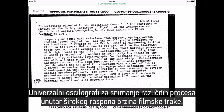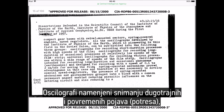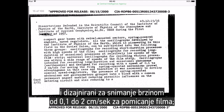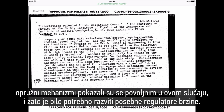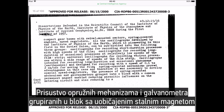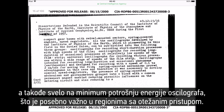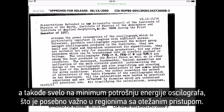of the film strip. Oscillographs intended for recording long duration and occasional phenomena, earthquakes, and designed for recording with a speed of 0.1 to 2 centimeters per second for moving the film. Spring-operated mechanisms proved advantageous in this case, and therefore it was necessary to develop special speed regulators. The presence of spring-operated mechanisms and galvanometers grouped into a block with a common permanent magnet enabled reducing parasitic influences on the metering circuit, and also reducing to a minimum the power consumption of the oscillograph, which is particularly important in regions with difficult access.